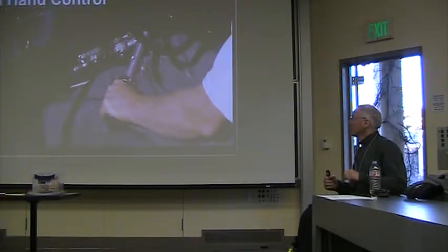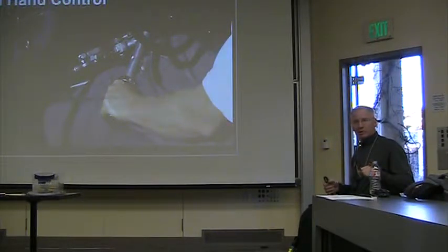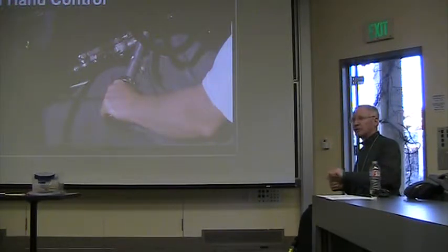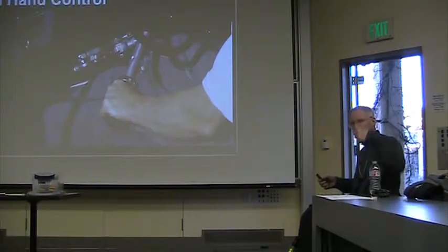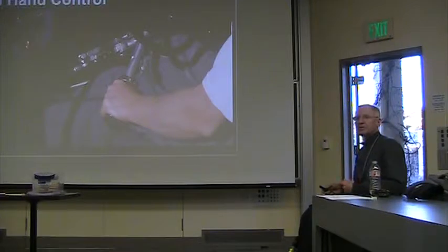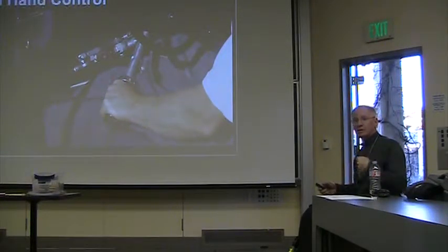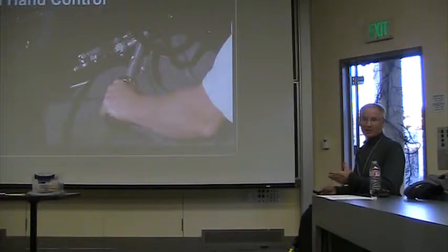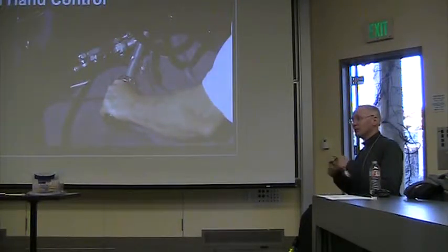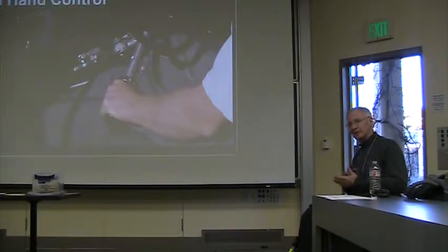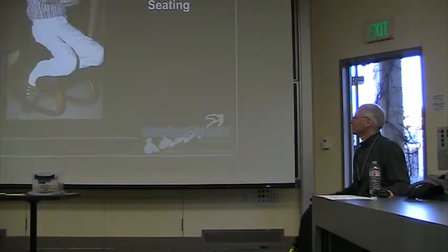I wanted to drive a car with a stick shift. Most hand controls are all for vehicles with automatics. So brake is always push, and then gas is either rotate or twist like a motorcycle, or pull or something. So this one I set up with twist for throttle, push for brake, and down for clutch. So I could be on a hill and I could have the brakes in, the clutch in, and put the gas on and slip the clutch out and let off the brake just with one hand. We couldn't find anybody to manufacture this. It's kind of a high liability thing. So we put the plans for this on our website, and people write, and they sign a release, and we send them the plans. Quite a few people have built these hand controls.